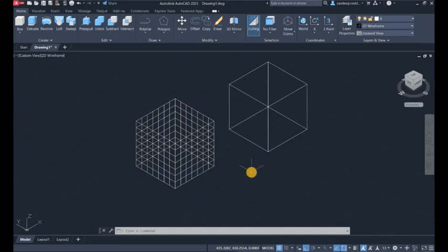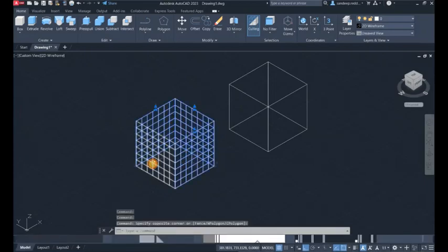So have that habit of drawing 2D objects in the XY plane using the polyline function rather than the line function, because as you can see, it just creates surfaces. You can remember this: if you extrude a line, you get a surface, a 2-dimension surface, and if you extrude a 2-dimension surface, you get a 3D solid. Okay, you have no need for these surfaces, so I'll delete them.